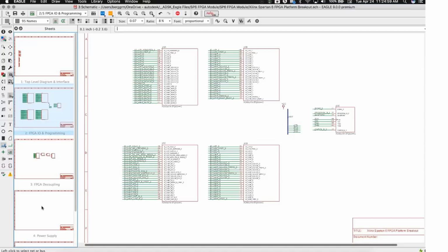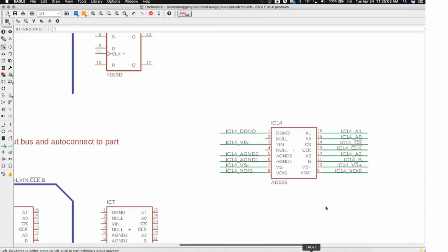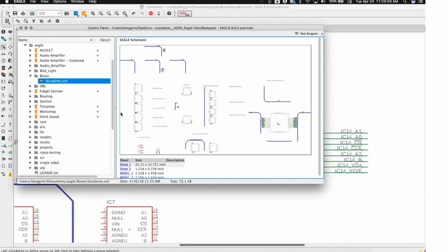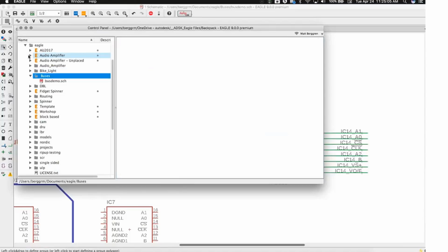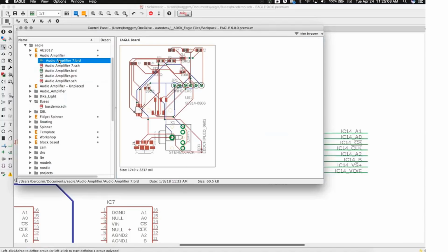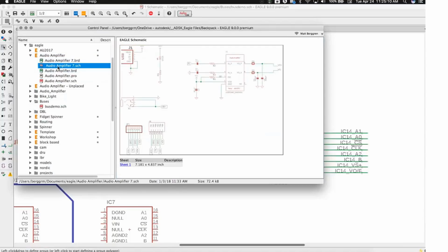Now, I want to quickly bounce over to another feature which is super cool in Eagle version 9. If it's cool, before we jump to that one, I wanted to also mention that you don't have to start from the bus. You can select a set of nets, right-click, and you also have the option to make a bus from the pre-selected set of nets.